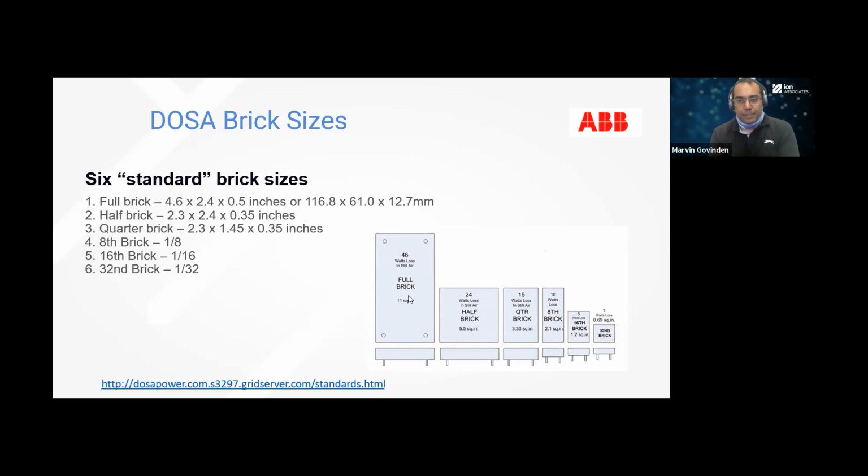So the power density is important. The more power you can pack into a smaller area, the more attractive it may be for an application. If it's a card for a telecom rack, where you save board space and the whole size of the rack can reduce considerably, that tends to mean also that the heat generated in that area will be higher. So your thermal solution has to be better. And hopefully the technology has improved so much that it's not generating as much heat as say 5 years ago. But yes, you can save board space, and that can be attractive.